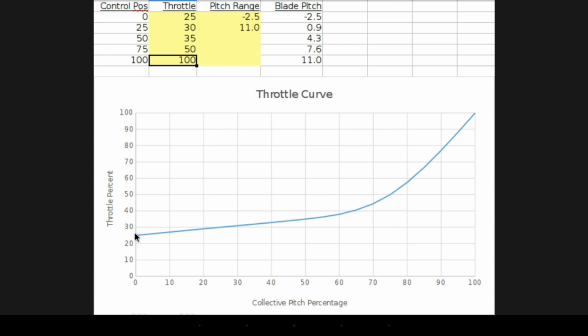Typically 35 to 40 seconds at ground idle, rotors turning, will warm that engine up enough so that you can start feeding power to it and increase the power without damaging the engine. So as we increase the collective pitch, the throttle ramps up to somewhere in this about 25% throttle range. I think I've got it set at about 25%. The governor becomes active in this helicopter.